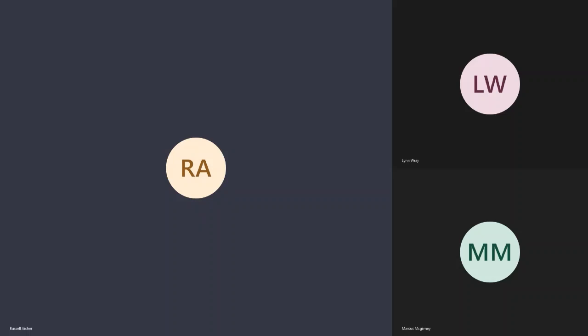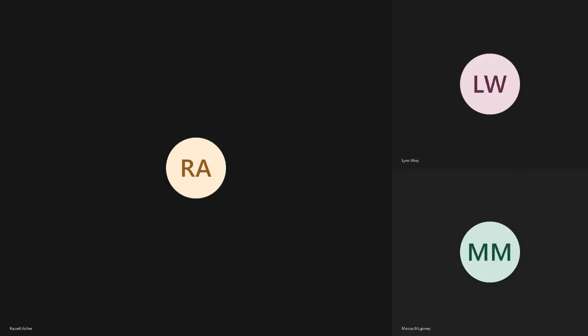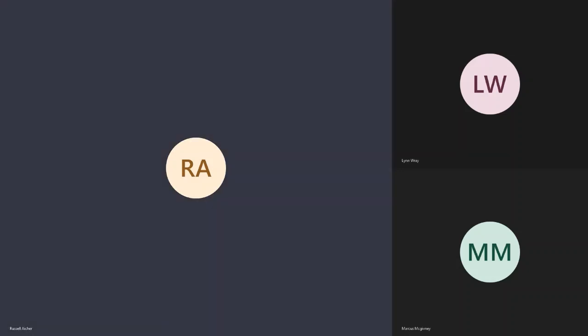And then somewhere, if that's all you have, you just have a point layer, that's all you need. But then if you sort of build that into a line layer, now you actually have to store not only the coordinates for each point, but which point connects to which. And then if you have a polygon, you have to store all that and the fact that it actually closes somehow, right? But still, in the software, in the background, the only thing that's storing the X, Y coordinates are the points. There's no real information on a polygon in the inside. It's the nodes and the vertices that make up the boundary that are being stored as coordinates.